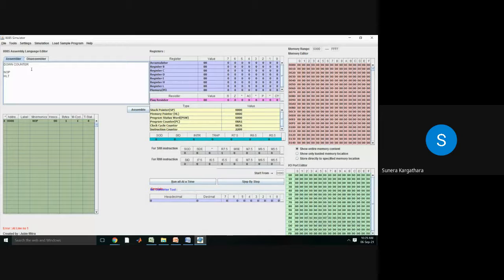I'll send it to the output port, and in between two count I'll write NOP, NOP, NOP. So that basically performs nothing, right? It will not perform anything. The process will not be executed. Any process will not be executed. It will only be used to provide a delay, some finite delay in between two count values. I hope you are getting it, right?